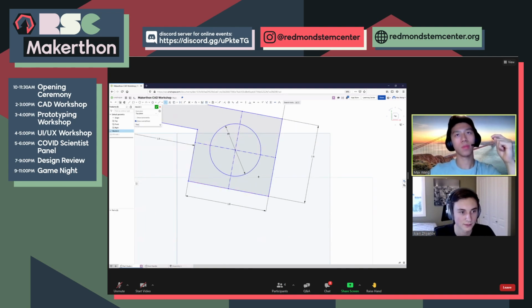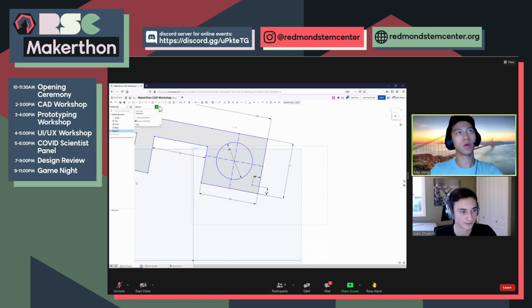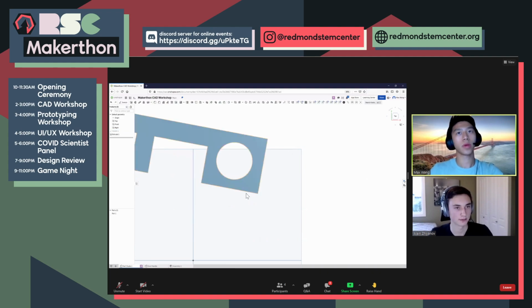Let's make a point here and let's dimension it. So I'm going to use the dimension tool and just dimension this point in context to these walls. Let's call that 1.135. Oh, let's not do that. 0.2. Okay, 0.2. That's good. And let's do the same thing over here for this wall. 0.2. Looks good. Alrighty. Press check.